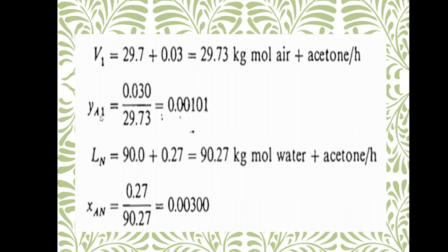If we want to know the mole fraction of acetone in this leaving V phase, the V1, that would be this acetone unrecovered divided by the total amount of air and acetone. So this is the mole fraction of acetone in the leaving V1 phase.